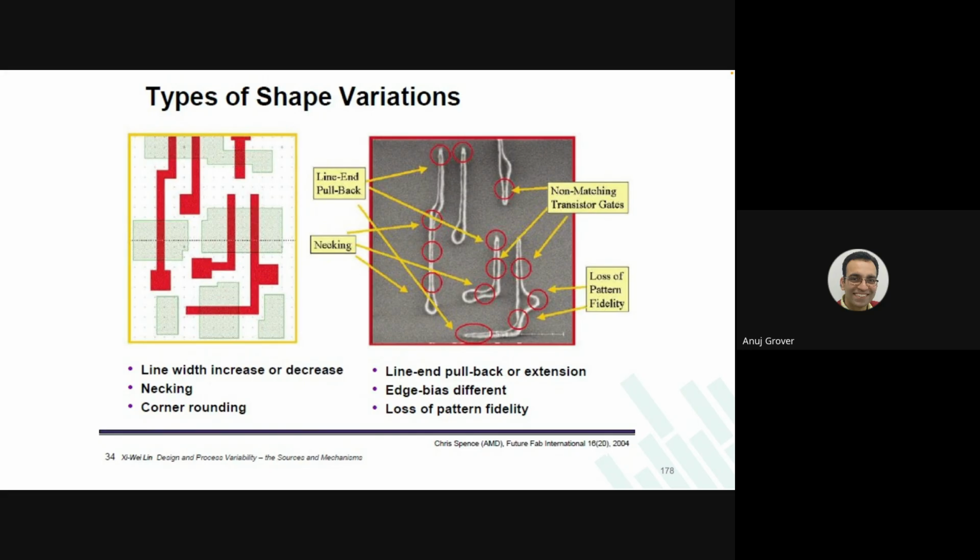We already saw part of it, or evidence of it, even when talking about a regular high density memory cell. With a beta ratio of 1 itself, the cell ratio of 1 itself, I finally had better yield than with a cell ratio of 1.4 or something like that. So denser cell, better yield.